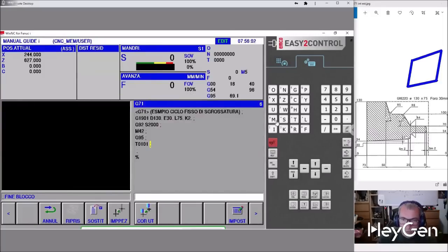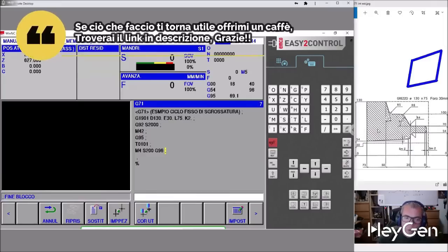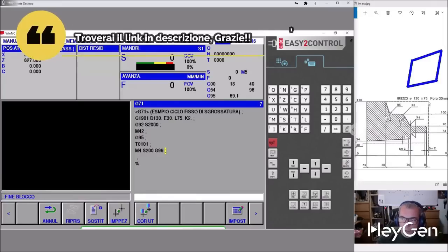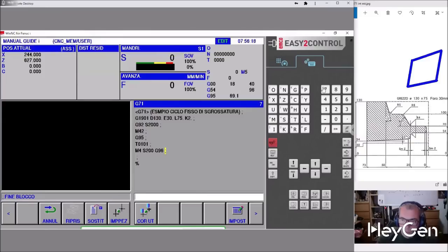The graphics section provides a visual representation of the tool path. The external general tool is selected based on material compatibility and machining requirements. The 95-degree approach angle and 80-degree insert angle optimize cutting efficiency. By entering M4 S200, G96 and EOB insert commands, we set spindle speed and cutting parameters. The G00 X300 Z0 command positions the tool quickly to the starting point.